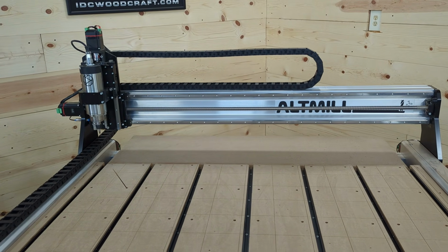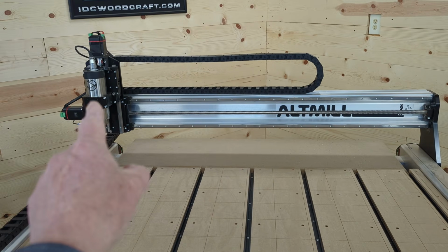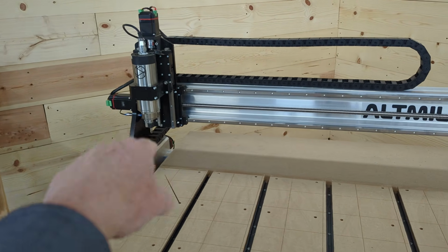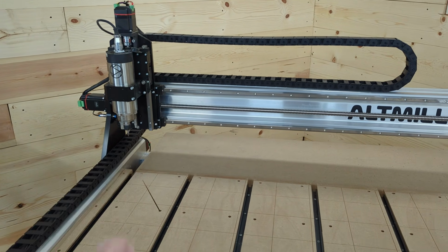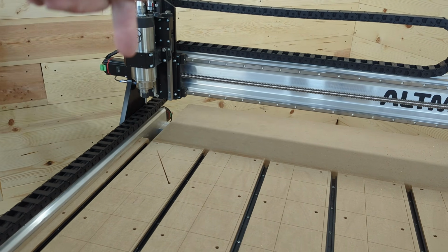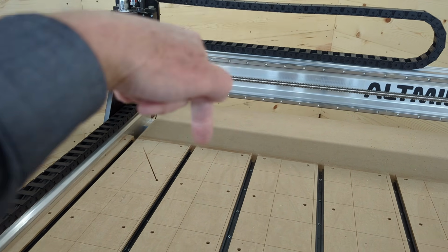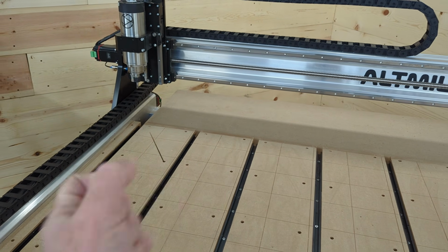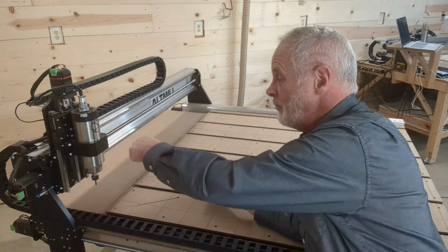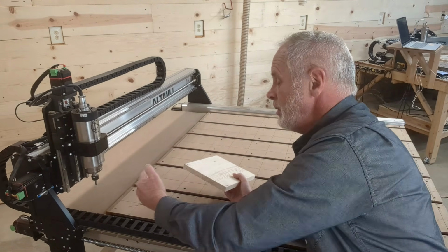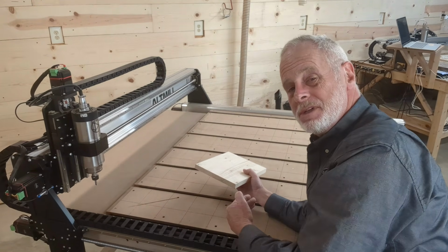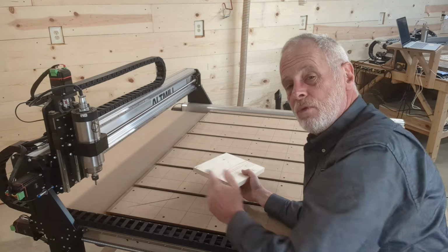The second thing you want to take into account with your Altmill is the home position. So all Altmill CNC routers have a home position in the back left corner of the machine. And that is the point at which we will start our grid lines, where when the machine is home, it'll dive straight down and start carving. Why is that such a big deal? It's because when you actually start carving your grid line from the machine home position, every grid line is going to be a factor of 4 inches from that home position, or 100 millimeters in both directions.